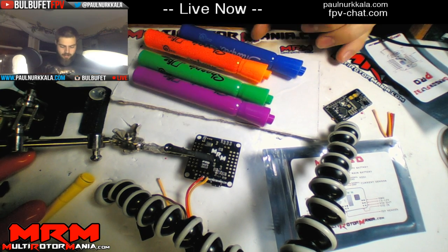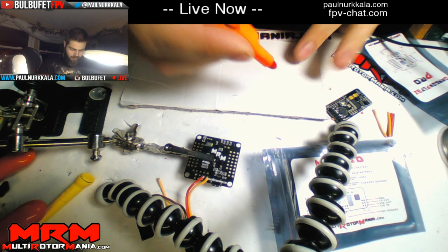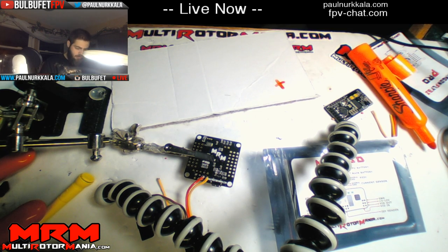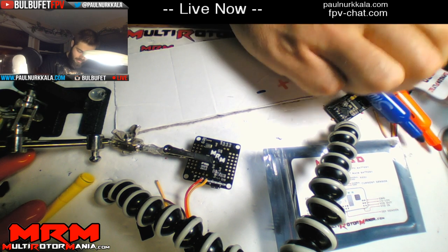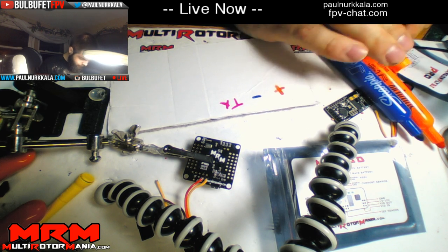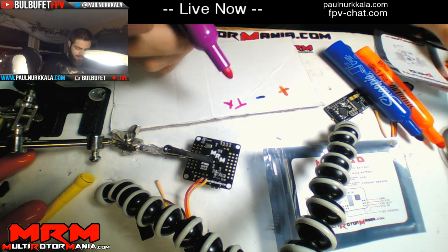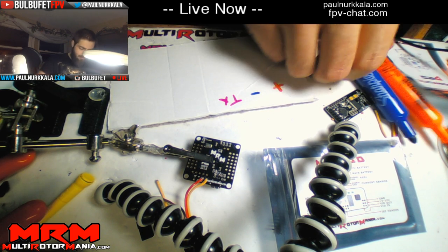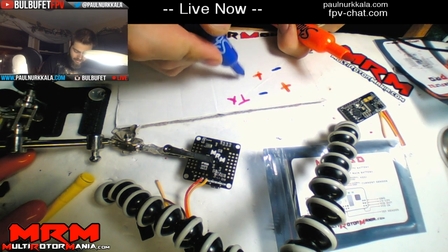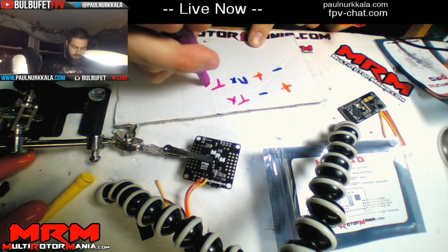So this is, we have positive, negative, TX. Wait, is it TX? No. Actually, I screwed that up already. We have ground, positive, RX, TX. Okay, this is the flight controller.